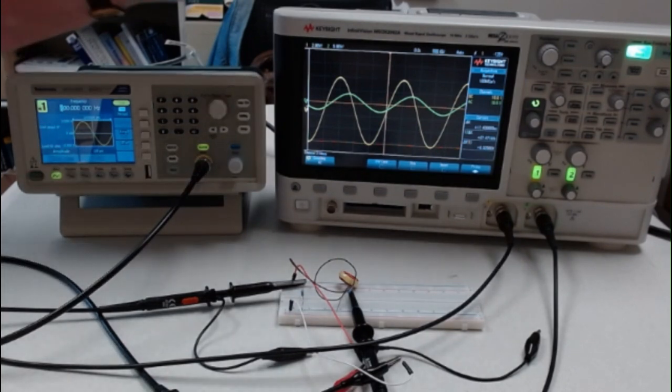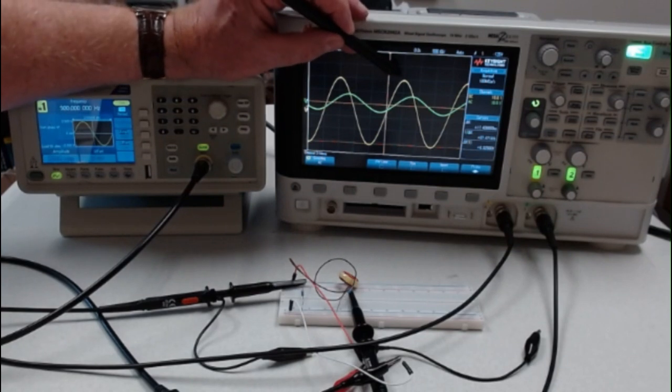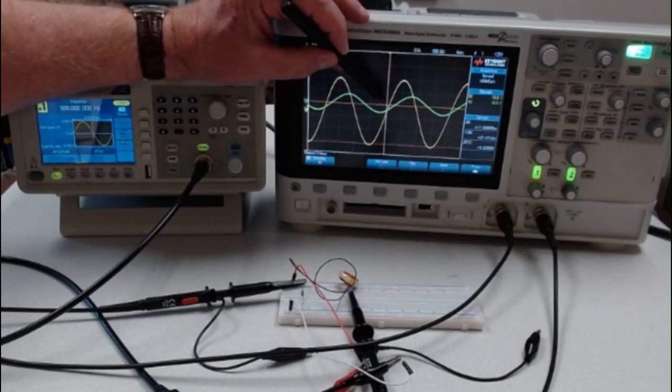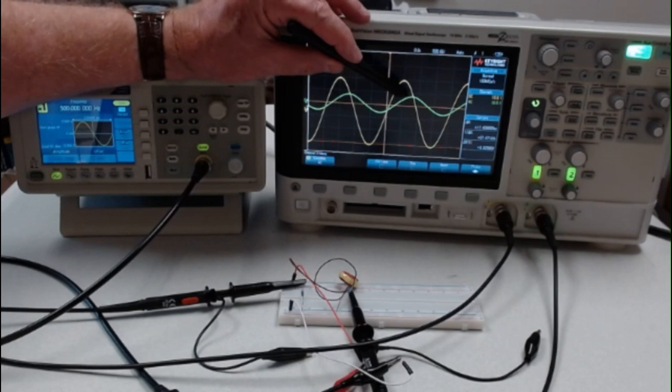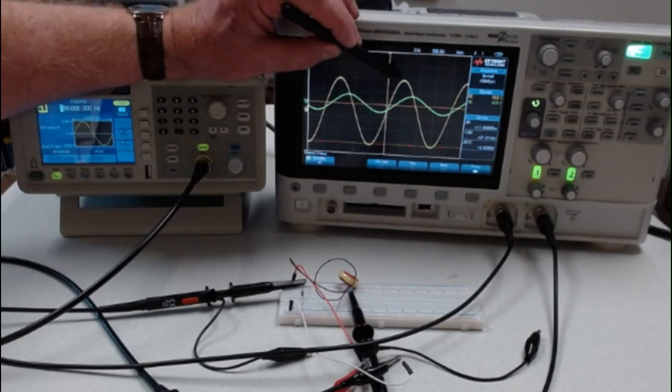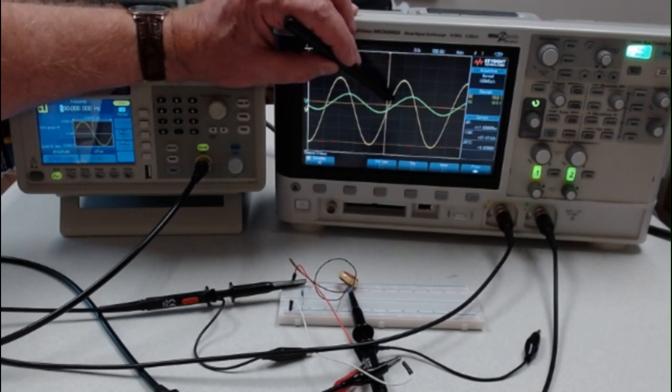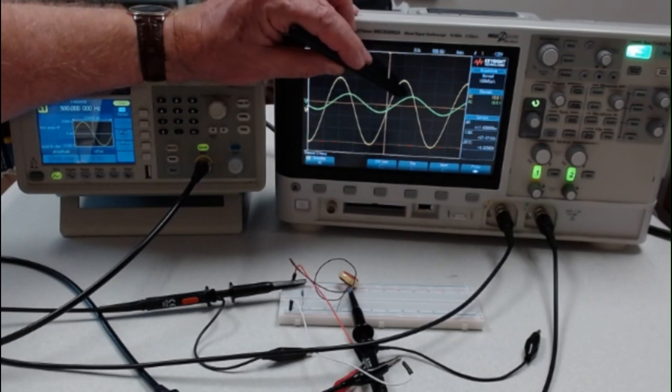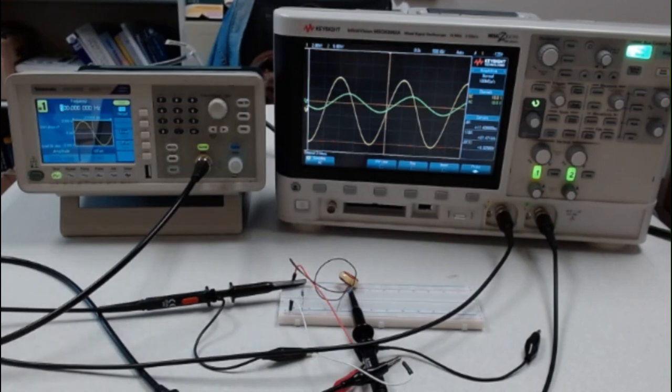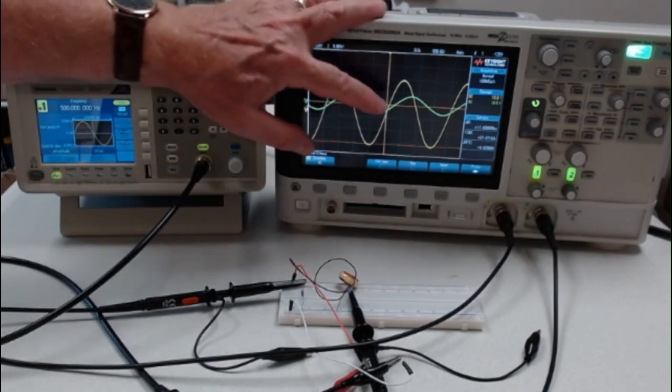Our phase angle changed dramatically when we went from 300 to 500, and our amplitude went down a little bit. Here's 0 to 10, and we're a little over, maybe about 3, from about 1.2 down to about 1.5 up. So that's about 2.7 or about 3 volts amplitude. So our peak to peak output is about 3 volts. Input is about 10, output is about 3.